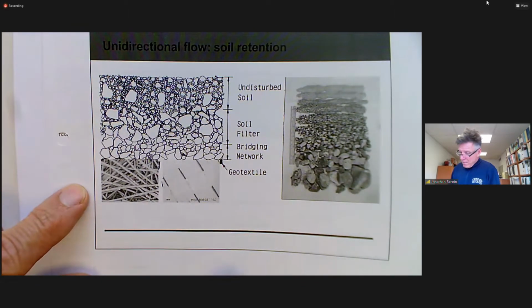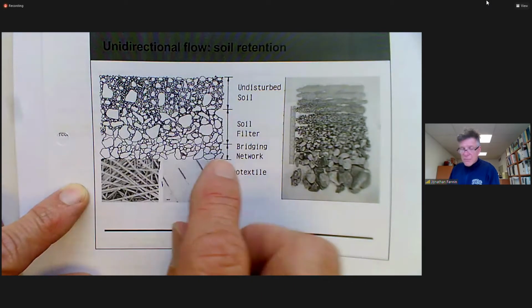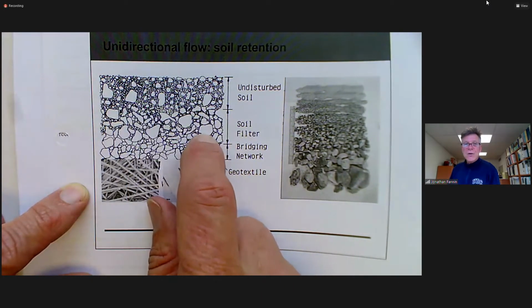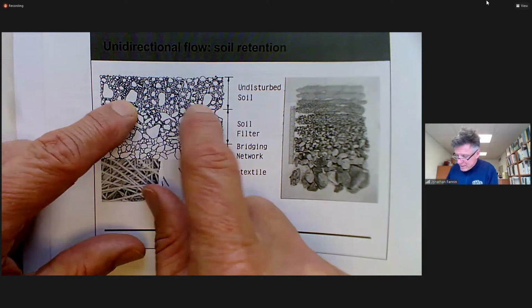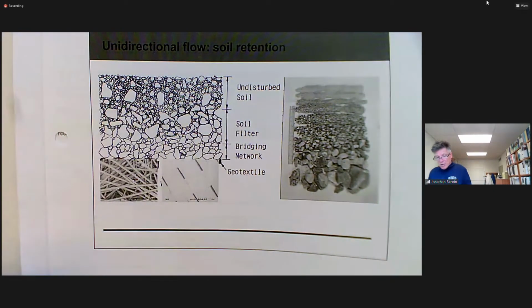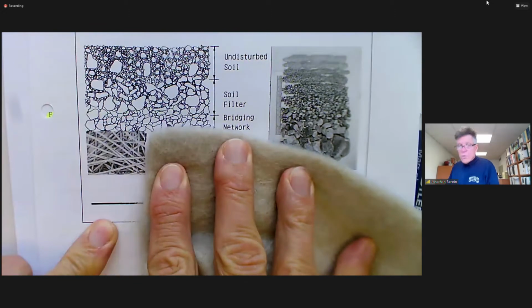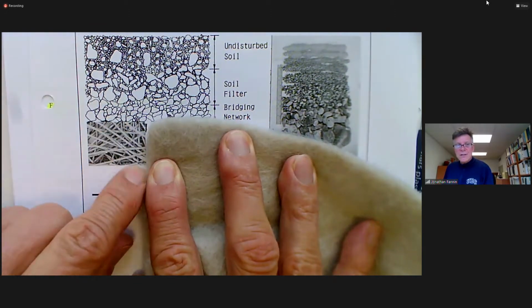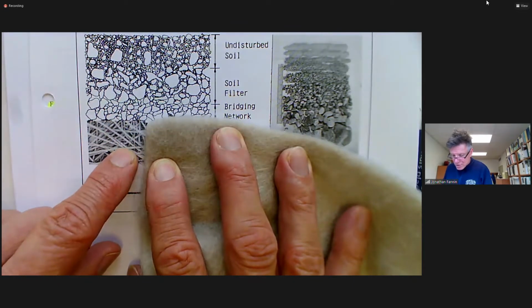Okay. Can you imagine that this is the soil, this is the base soil. Now we've got various particle sizes from very coarse, let's find the largest one, call it D100, let's call these guys D85. And you come along, let me get my geotextile, and we put a non-woven geotextile there, right? There's a non-woven geotextile. Let's call this an enlarged photo of the pore size architecture. And you see what we're doing?